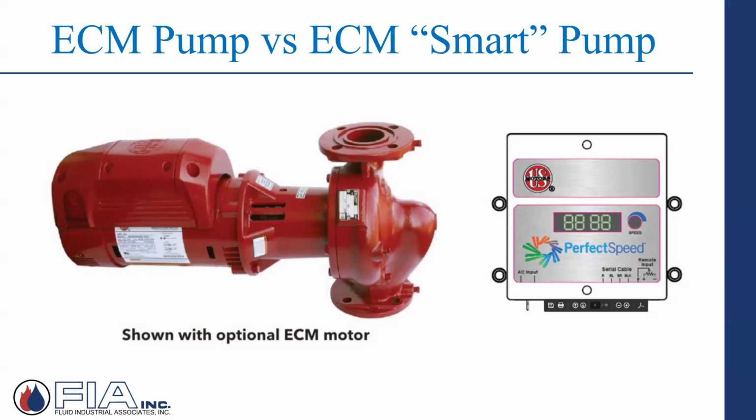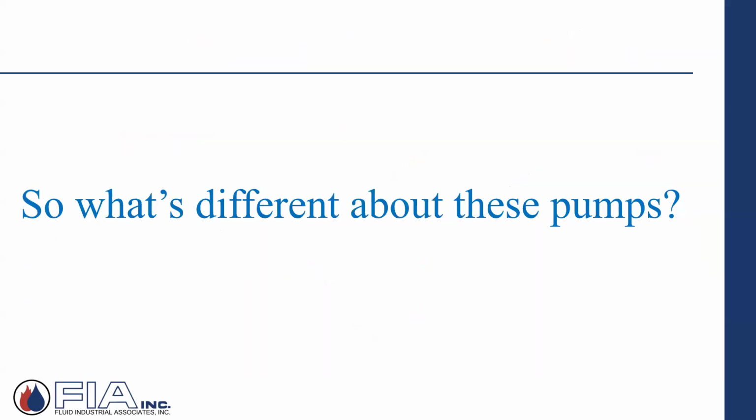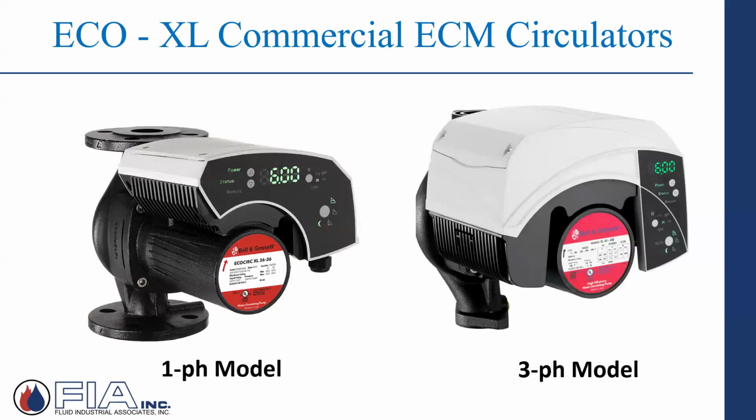It's got an ECM motor and it can do some speed control, but it's going to need something, either an external signal coming to the pump, or on the motor itself, they'll have a little gauge or potentiometer where you can select a particular speed, and the pump is capable of changing the RPMs to whatever you select. But it doesn't have these drives on board.